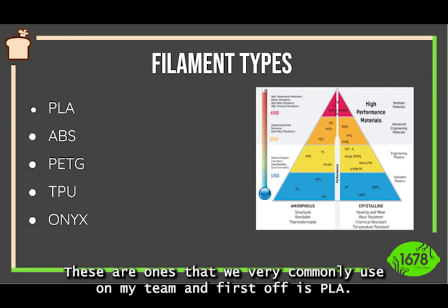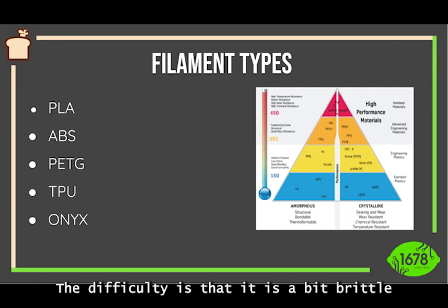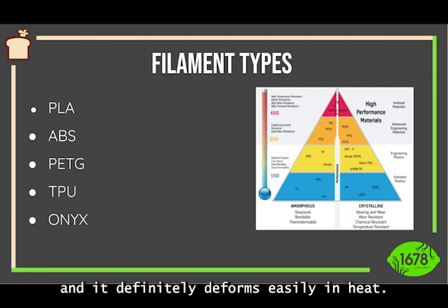And first off is PLA. It's very easy to print, and it produces a very smooth and detailed part. The difficulty is that it is a bit brittle, and it definitely deforms easily in heat.